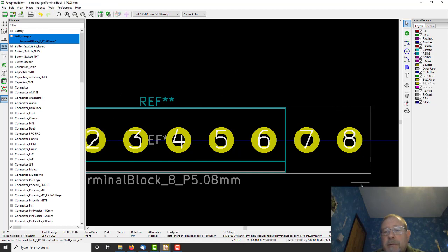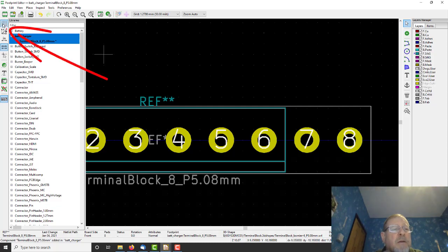Okay, so I've started moving these graphic elements so they hook around the newly added pins. The cursor sticks to the grid, which means you can't really, or you can. So look at that white line, I can't select that because I can't get on it. That is now supposed to stick to the grid, and the grid is displayed as dots.